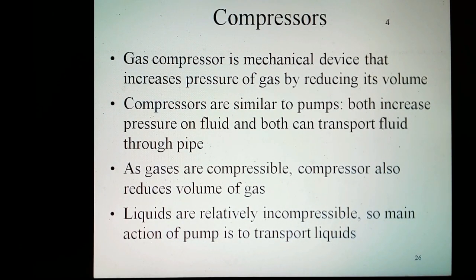Compressor. The gas compressor is a mechanical device that increases the pressure of a gas by reducing its volume. Compressors are similar to pumps. Both increase the pressure on a fluid and both can transport the fluid through a pipe. As gases are compressible, the compressor also reduces the volume of a gas. Liquids are relatively incompressible, so the main action of a pump is to transport liquids.